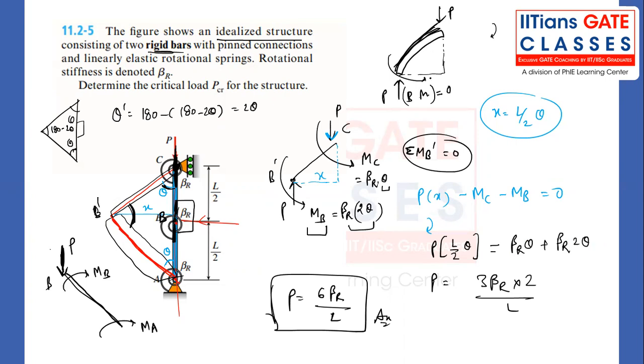But in our case, we are taking the bending moment to be 0, because we are treating EI as concentrated at a particular point, not spread throughout the length of the member, because it is the ideal one, not an actual one. Just for our understanding of what buckling of a column means and how stability is related to it, that is what we are learning through this idealized structure. Our purpose is to get P-critical. Then we will throw this idealized structure away and design our actual beam, actual column.